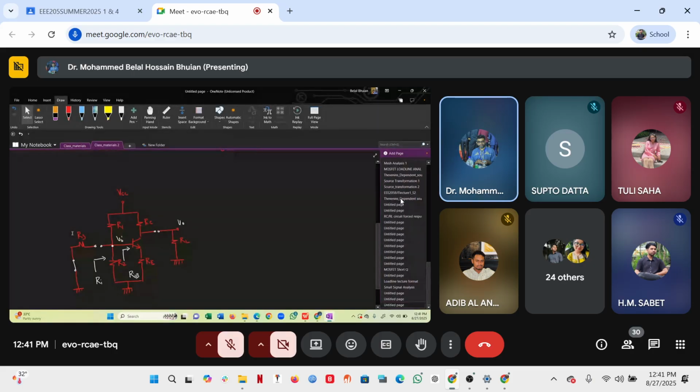Notice the left hand side and the right hand side of the circuit are disconnected. So we are only left with a voltage divider biasing network, R1, R2, RC, RE, and VCC. So if you analyze this, we get DC IC. So let's assume that we have analyzed it, and in fact, we have analyzed it. So IC equals beta times (VTH minus VBE) over (RTH plus (1 plus beta) RE).